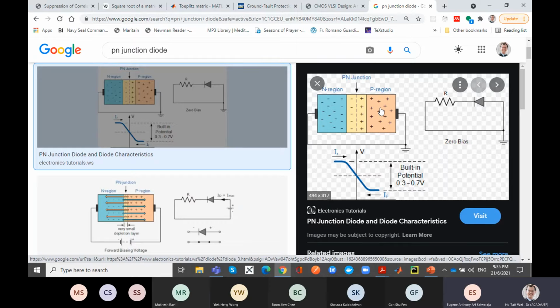Yes. It's coming back. When I have a p-type, I have an n-type. So what happens when you have a p-type region and an n-type region? N-type has a lot of free electrons, p-type has a lot of free holes. Then you join them together, you touch them. Okay, I mean, this is conceptually, when they actually build it by just changing the doping. So what happens is the free electrons suddenly see here got a lot of holes here. So the electrons will start flowing over to the other side. And then the holes will start flowing over to this side. And then they recombine, right?